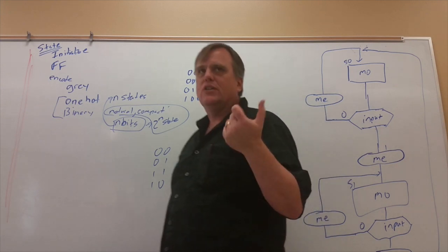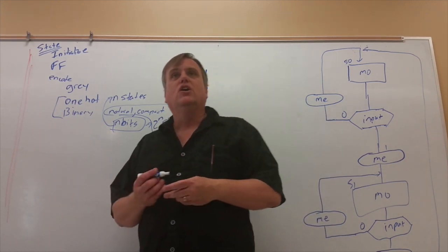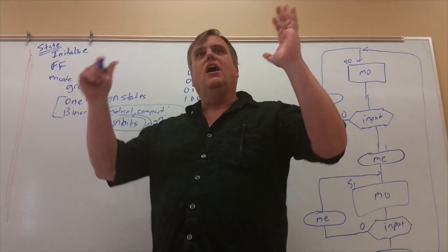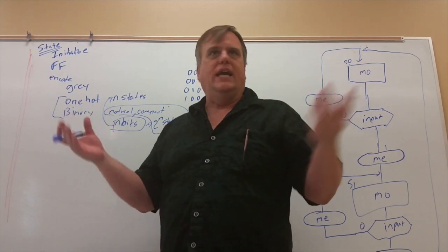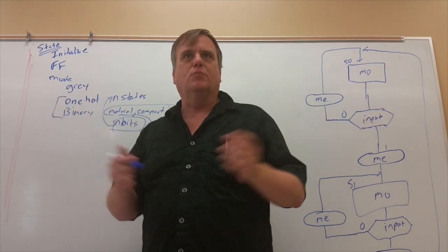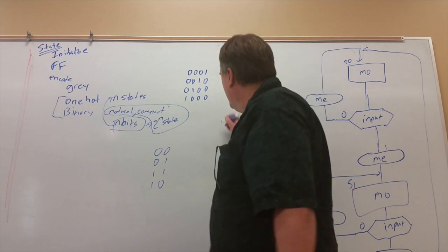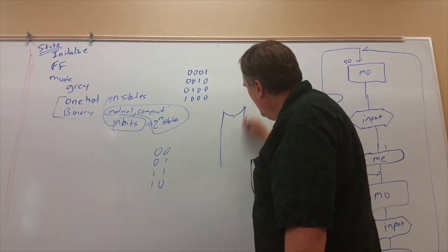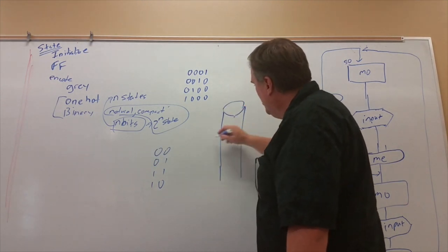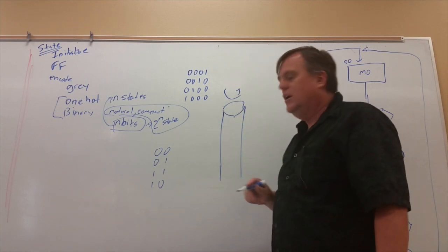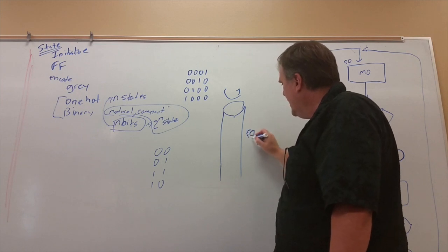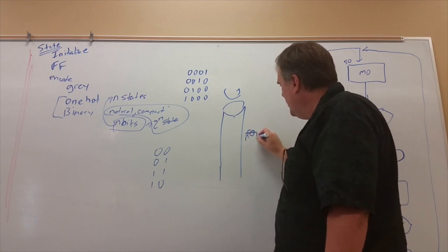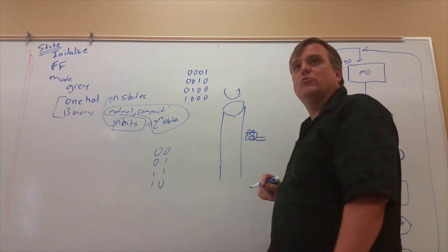So this is particularly, let's imagine I have an input device. Imagine I was dealing with, let's say I wanted to run a drill, or any other type of rotary machine. I could put on the shaft of whatever device I'm trying to run, rotating at some high speed, an LED that's shining, with a little wall between it, and a diode to read back out.